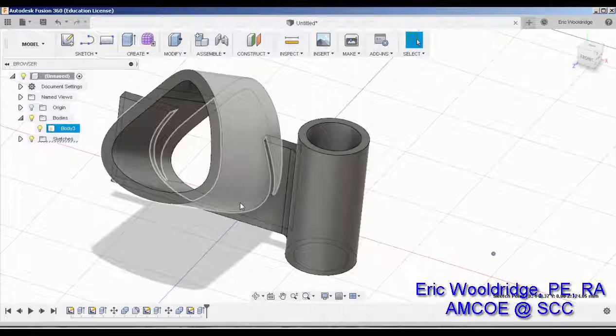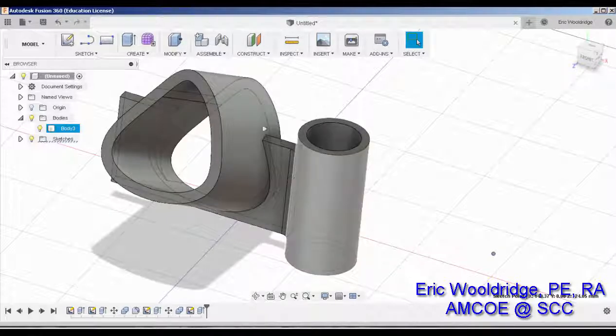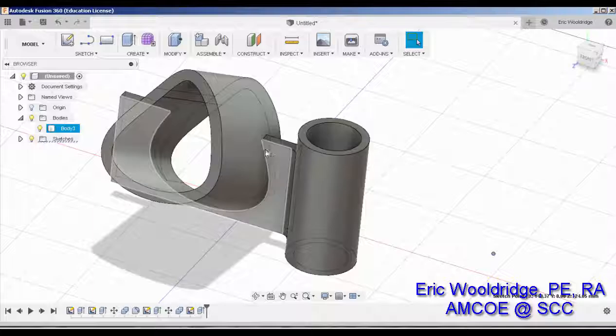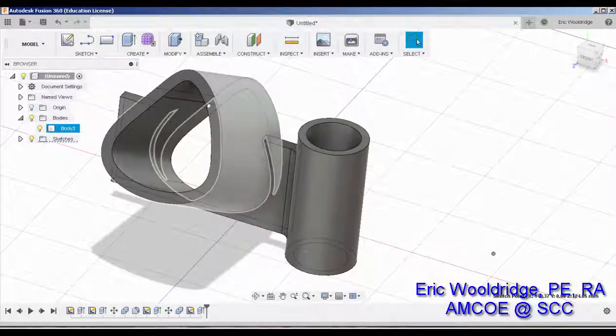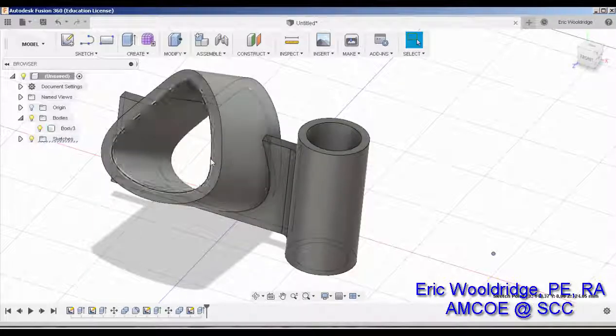So a handy little trick with the move tool to really think about if you just can't get your planes to be created the way you want to, and you can't get a sketch plane to behave at the right angle, or the geometry is getting complex and it's wanting to freak out with each other: draw your shape over on the side and then move and place it at the end to keep going with your project. And then, like I said, you can always come back to your original sketches over here and make simple and easy changes. All right.